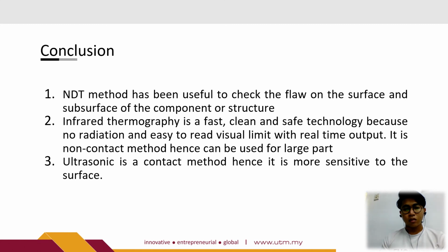It is a non-contact method, hence can be used for a large part as it can capture a wider thermal image for inspection in one go. Ultrasonic is a contact method, hence it is more sensitive to the surface, which only allows inspection of the surface it contacts, and it also consumes more time to inspect one large component. Okay,